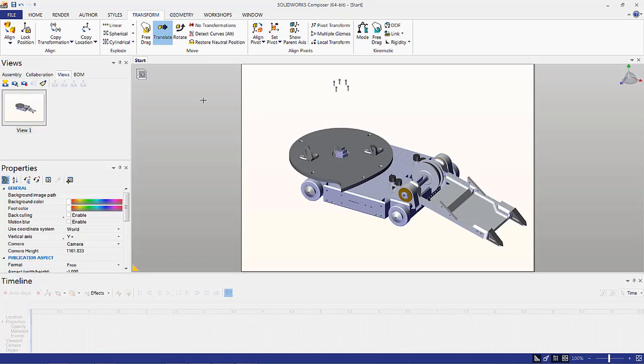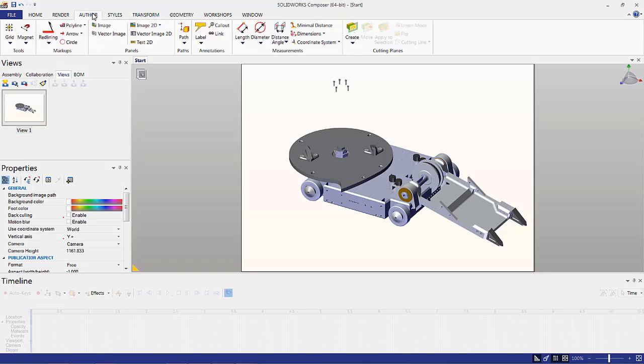Now to symbolize this move in the vertical direction, we'll go ahead and add a collaborator, an arrow. By mousing over the center geometry and holding the Alt key down, I'm able to pick up the axis that all those parts are lined up with and place my arrow on that axis so that even if we rotate the model, it's attached to that same orientation, that same 3D space as the screws came from.